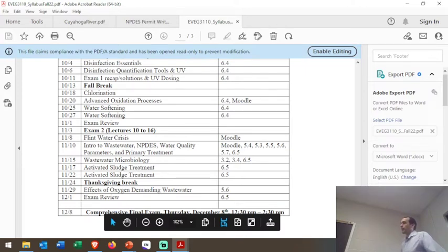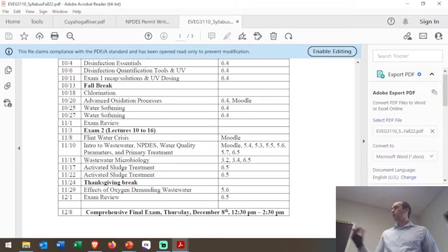And they do a lot of that removal in terms of digesting things, making them simpler, making them less hazardous potentially, and then collecting a lot of that mass into bacterial cells, which are then easier to remove physically, just sedimentation, to take those out, and then we can landfill the cells. That's a lot easier of a separation technique than applying the force required to get, let's say, an advanced membrane filtration system.